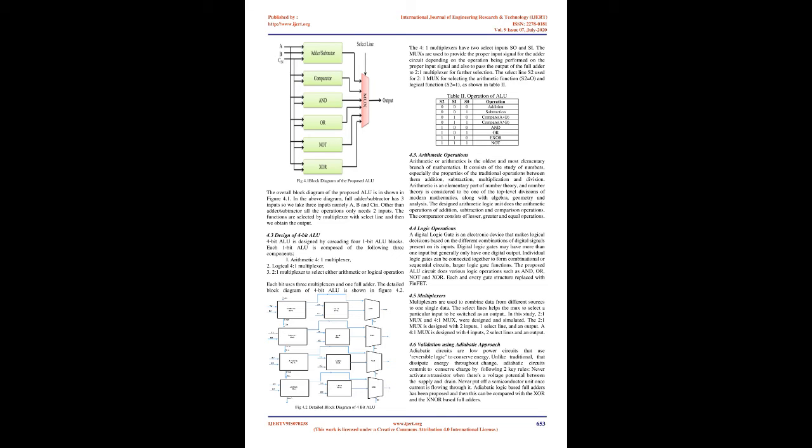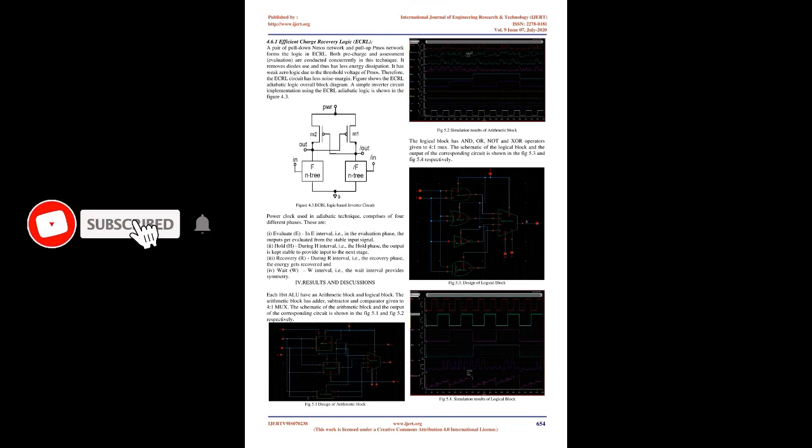3.2 Working principle of FinFET. The working principle of a FinFET is similar to that of a conventional MOSFET. The MOSFET can function in two modes, enhancement mode and depletion mode, for both P-channel and N-channel MOSFETs. In depletion mode, the channel shows maximum conductance when there is no voltage on the gate terminal. As the voltage changes to positive or negative, the conductivity of the channel reduces.